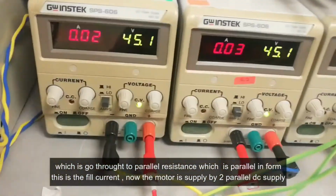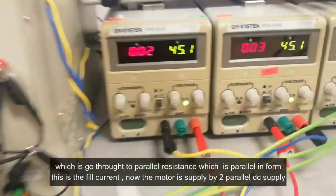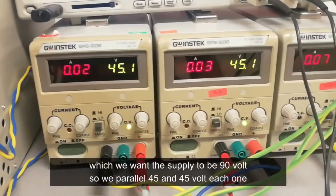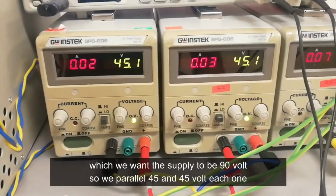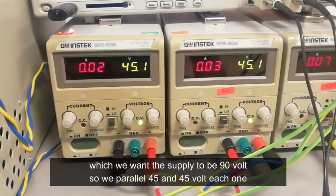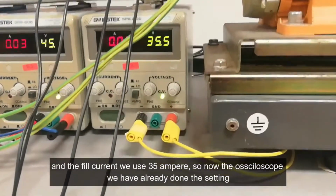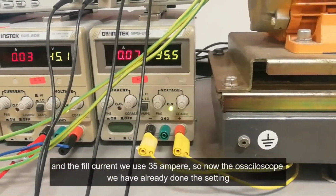Now the motor is supplied by 2 parallel DC supplies. We want the supply to be 90 volts, so we parallel 45 and 45 volt for each one. And for the field current, we use 35 volt.